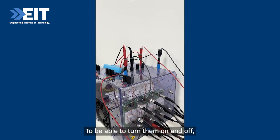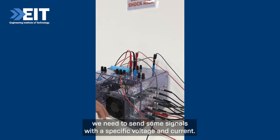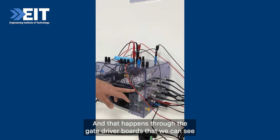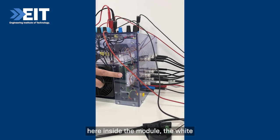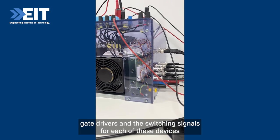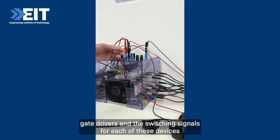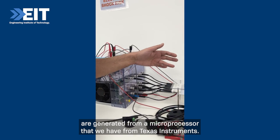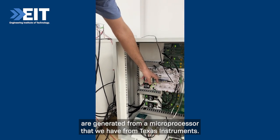To be able to turn them on and off, we need to send signals with a specific voltage and current, and that happens through the gate driver boards that we can see here inside the module, the white gate drivers. And the switching signals for each of these devices are generated from a microprocessor that we have from Texas Instruments.